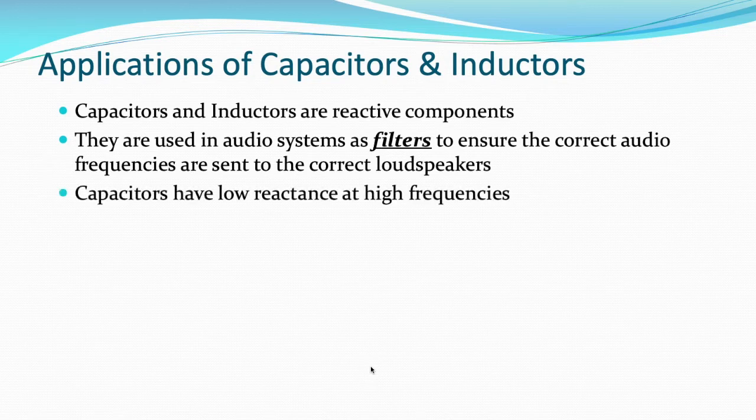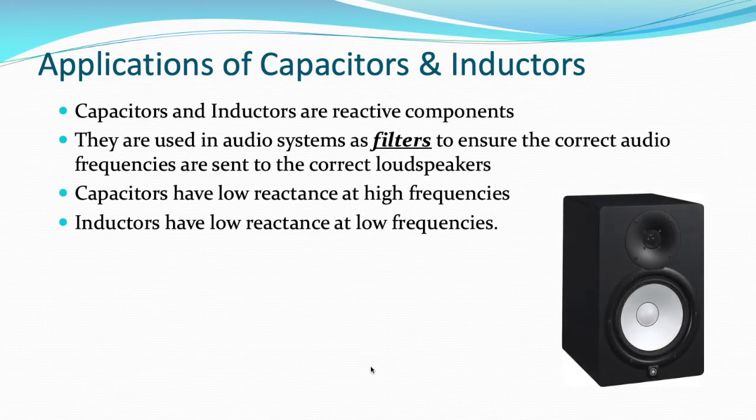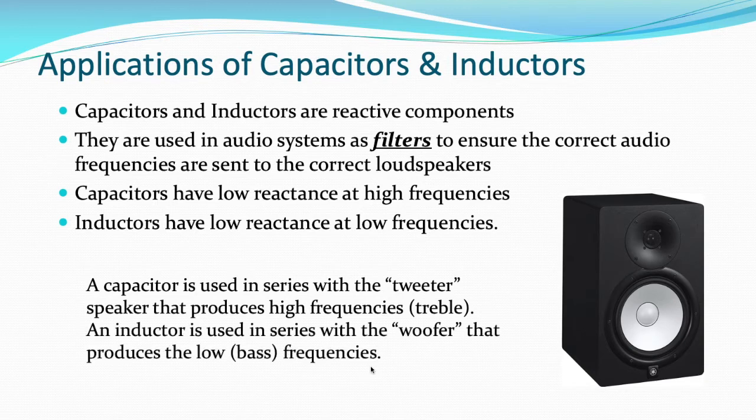So if capacitors have low reactance to high frequencies, and inductors have low reactance to low frequencies, then a capacitor is used in series with the loudspeaker that produces the high frequencies. It's usually called the tweeter. So a capacitor is used in series with a tweeter because you want your high frequencies to come out of that small upper speaker. And an inductor is used in series with the woofer that produces the low bass frequencies, so that it will block the high frequencies but allow the low frequency signals to pass to your woofer.